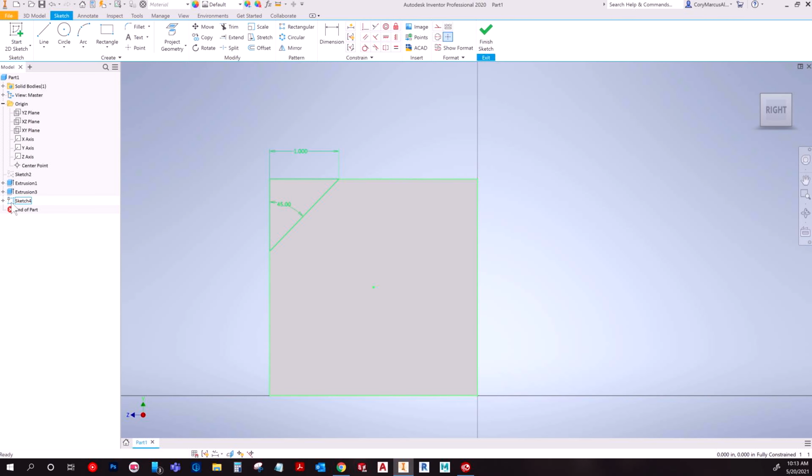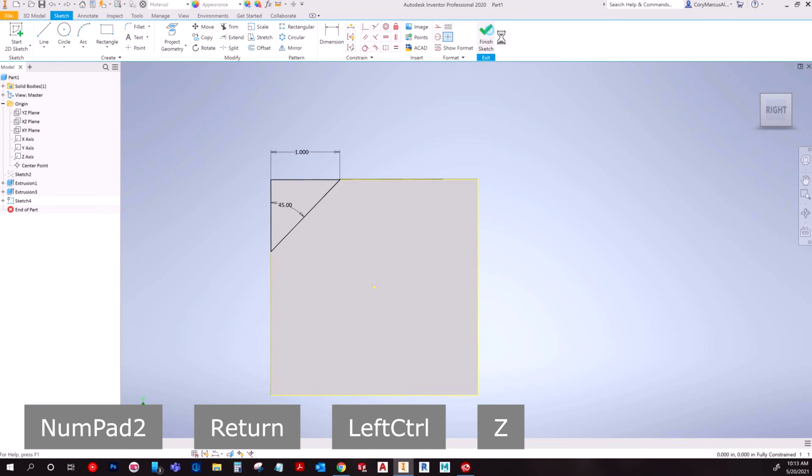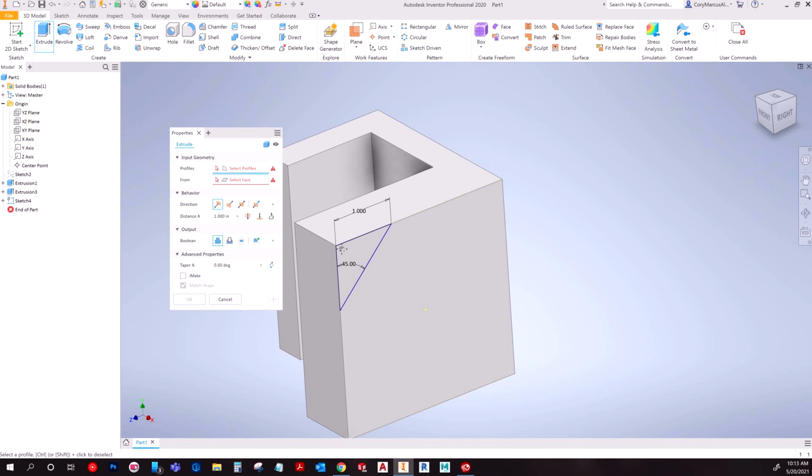That means that your sketch is probably fully constrained. You can double check that if you have a pen over here. You can hover and it'll say fully constrained, and down here to say fully constrained. And this is generally the way you track these things in a sketch. It's obviously different if you aren't in the sketch, you won't see it. So I'm just going to roll with that. And now you notice you can't see the fully constrained. That's what I was talking about. It's only at the sketch level.